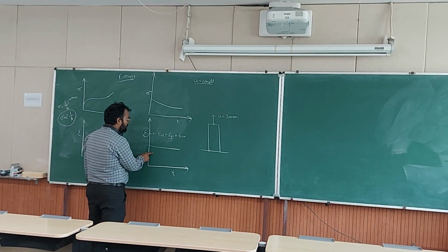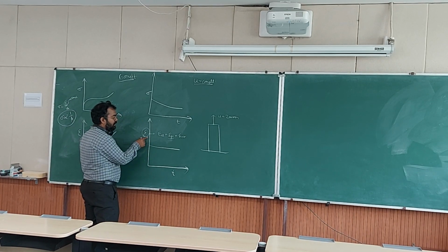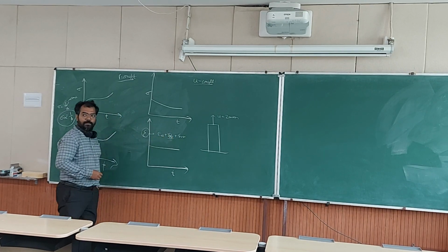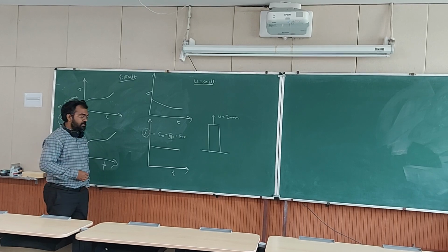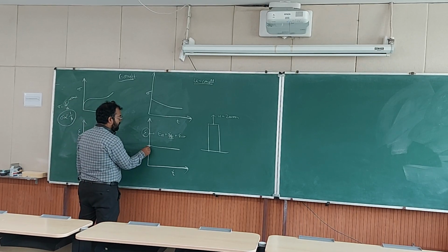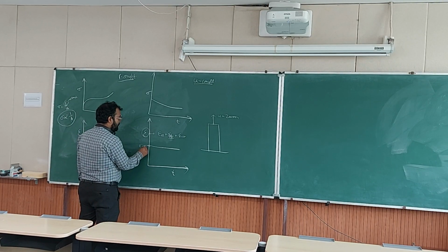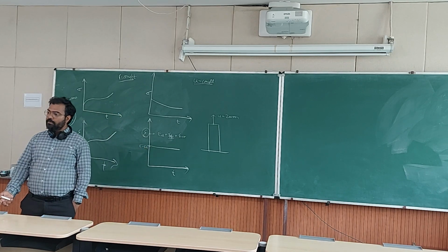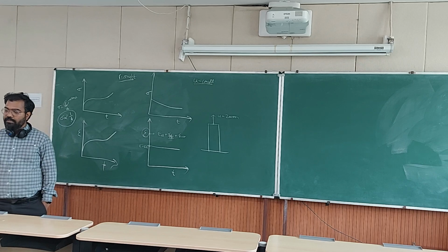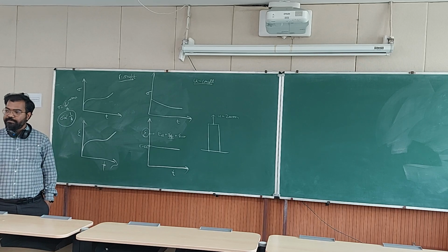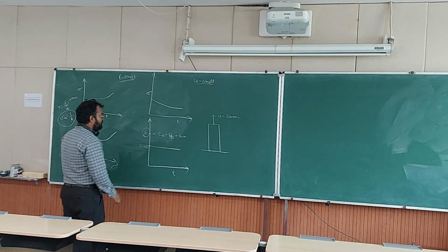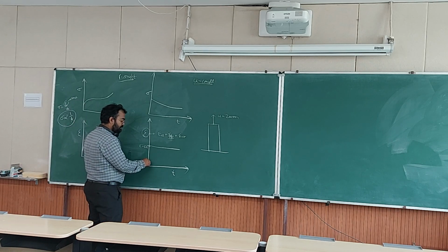Initially, suppose the strain is such that it doesn't cause yielding. So suppose this is 0. Then whatever strain you have here is elastic. Completely elastic, because time is 0. There is no creeping. Creep strain will develop with time. So as time increases, creep develops.